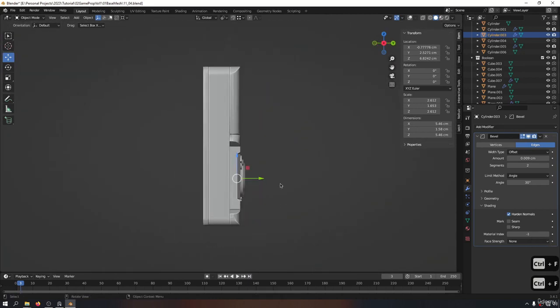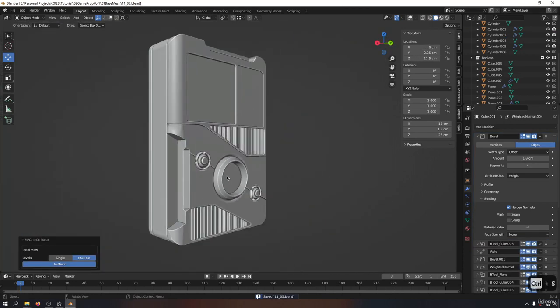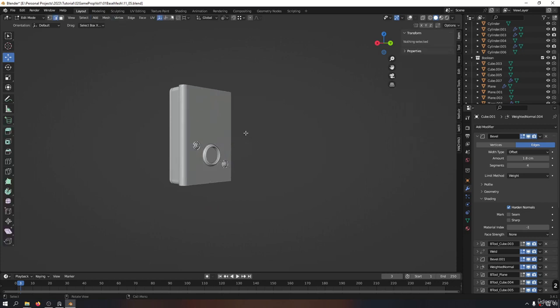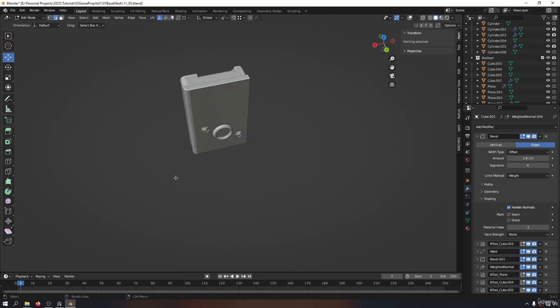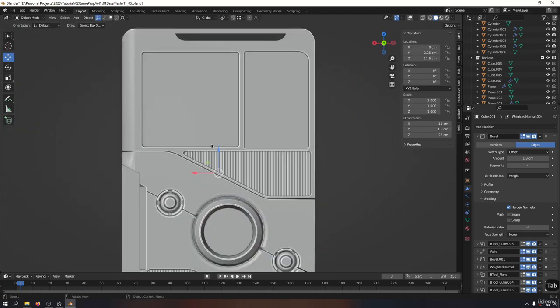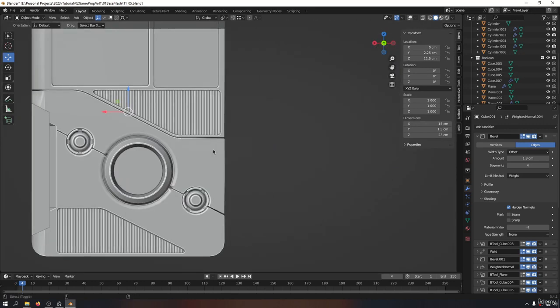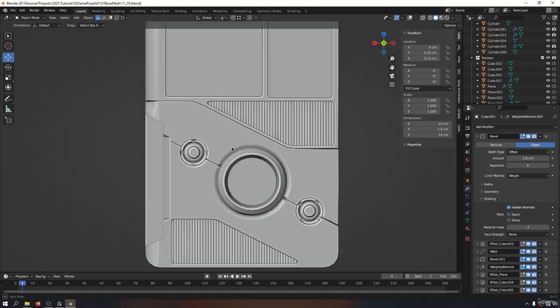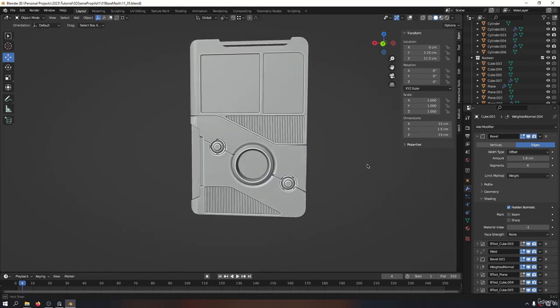And let's see how far it goes. Okay, it's very good. And now it's time to go and add smaller details. And this is the way that it goes. We first start with the big shapes, the things that really define the shape. For example, if I take this one and go in, you see now everything in here is based on this cube that we scaled and are changing. And now you see later on we went ahead and added smaller details and smaller until the point that we are going to very small points. And this is the way to create 3D props. You start with big shapes and then start to add smaller details later on.